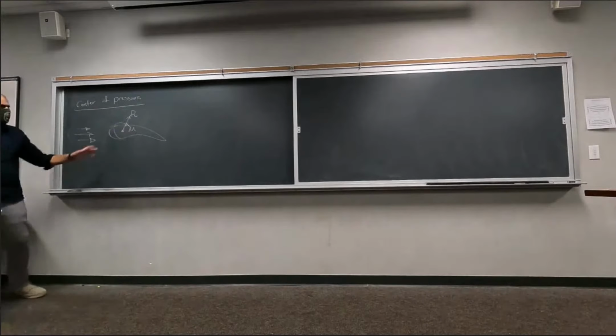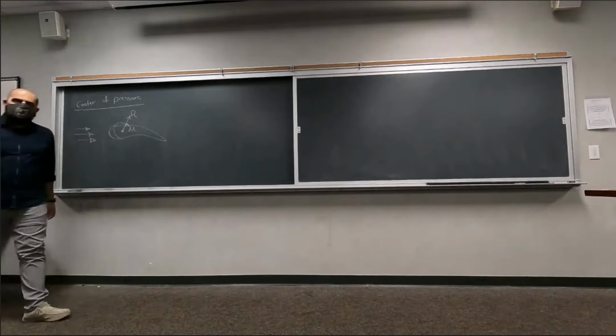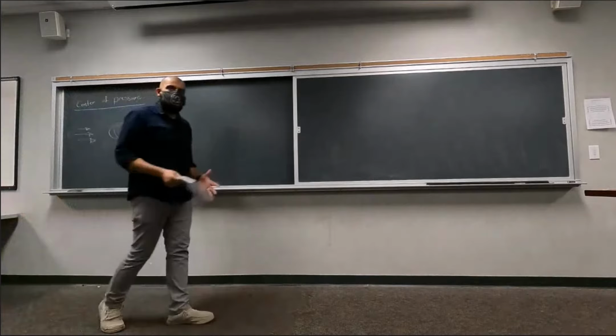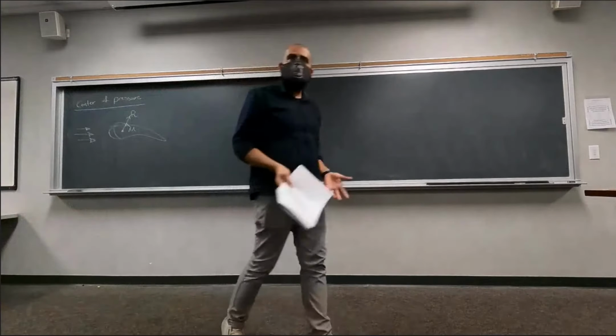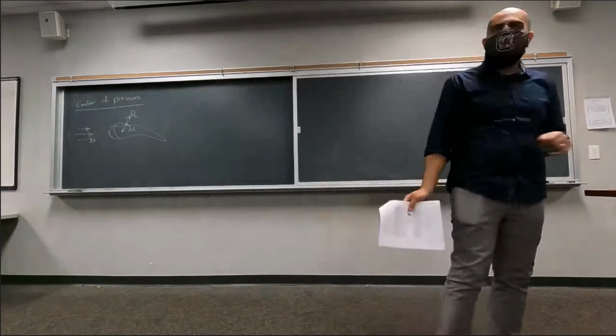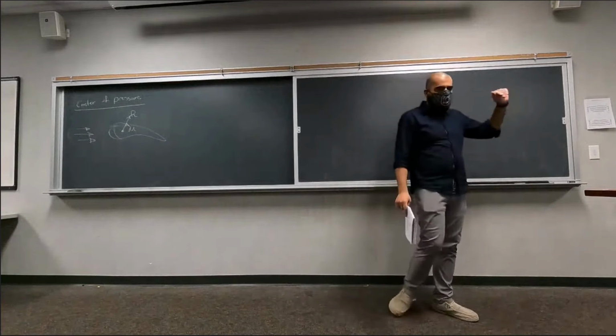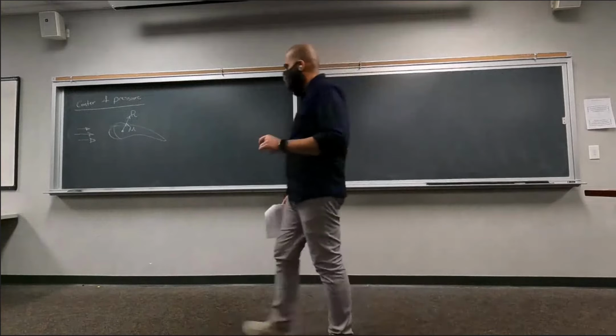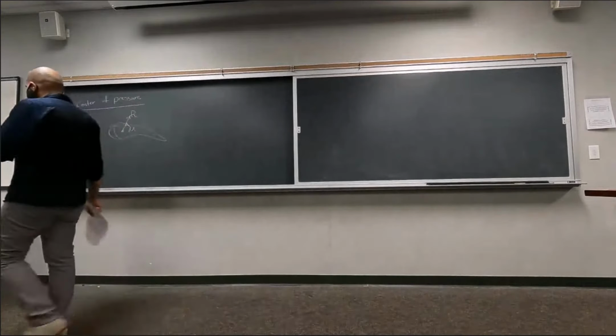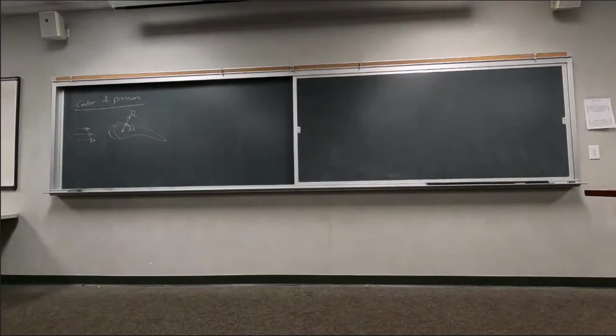So this resultant force and moment are the result of integrating the normal pressure and the shear stress over the whole surface, the lower and the upper surface of your object, right? And we have seen all of the ways to calculate those integrals, essentially, to calculate the final forces and the force coefficients in the previous lecture.